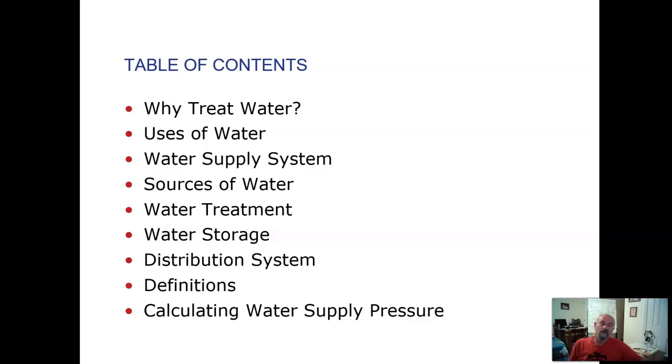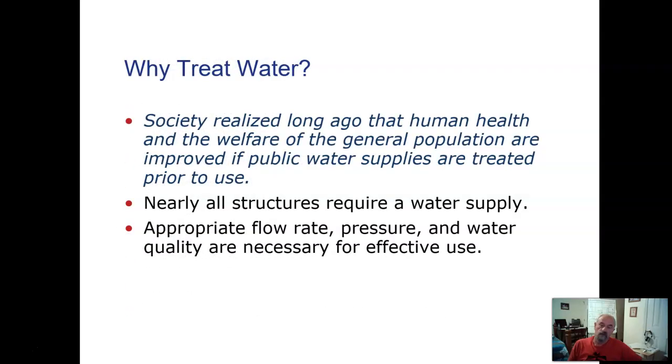And we will get into the difference between volume and pressure here. Some of you may have been in the shower at one time or another in your house or in some other place where someone flushed the toilet or ran the water, and then you had a huge drop in pressure. Your shower didn't want to come out. That is from volume, the amount of water, not so much the water pressure. And that can be caused by a lot of variables in a system inside of the house, depending upon how it was plumbed.